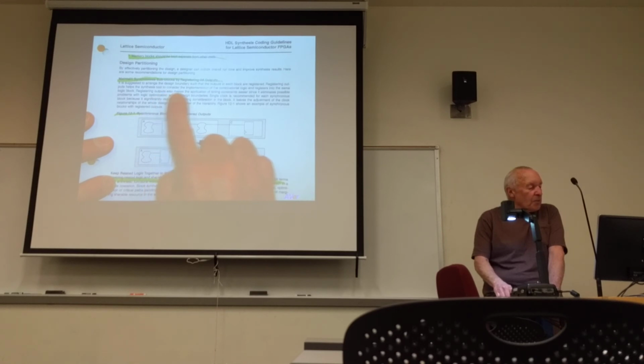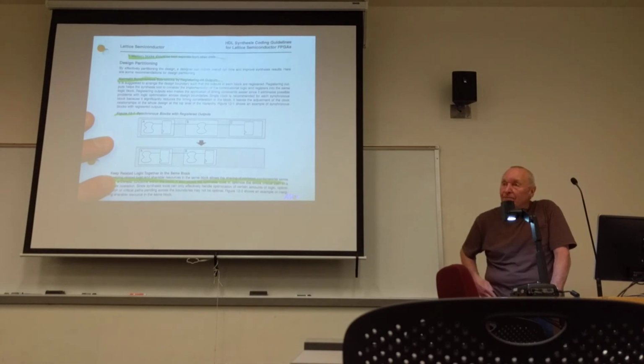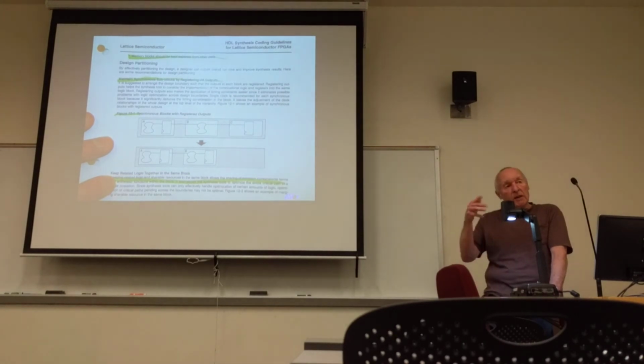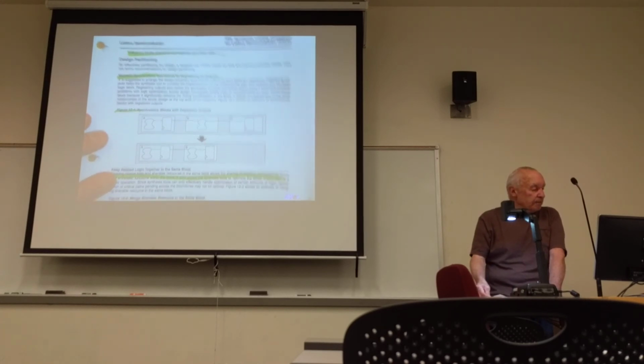Registered outputs makes the application of timing constraints easier. We're going to be talking in a future lecture about timing constraints. It makes it easier to analyze the timing. It makes it easier for the synthesizer to satisfy your timing constraints if you have registered the module outputs.